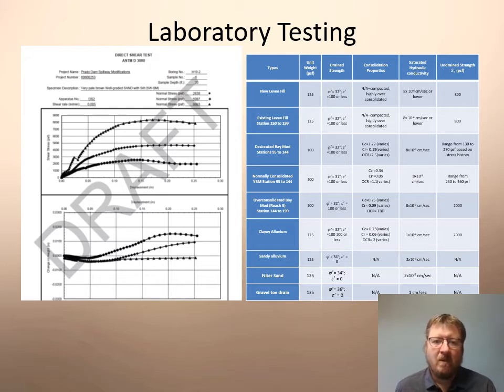For example, when we talk about using old or existing data to evaluate a current planning project, it's important to note that whatever that old project was, it was not performed for the same purpose as the geotechnical investigation being considered now. So there's a lot of uncertainty and interpretation that has to be made, and judgments sometimes if we don't have enough money to do investigations and lab testing in our current project. But it's important for everyone to realize that just because we have old borings and lab data, it doesn't mean it's the information that's needed for the current work.